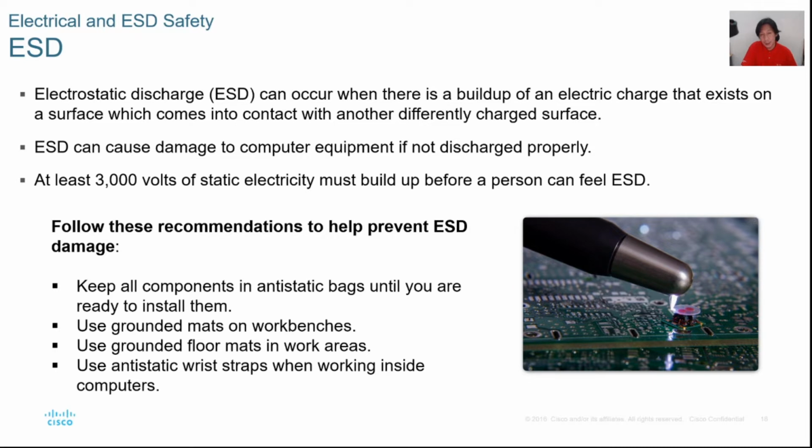I'll be demonstrating and showing you different examples of anti-static wrist straps. Before you remove any component of your desktop PC, you need to make sure that you're using what they call the anti-static wrist strap. Also, for electrical safety, you need to make sure that your computer is powered off.